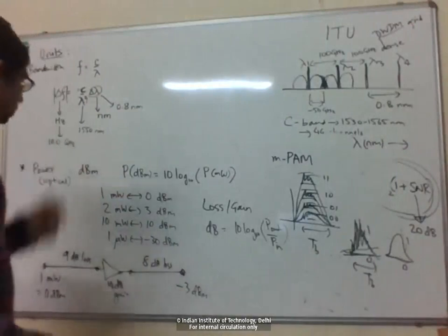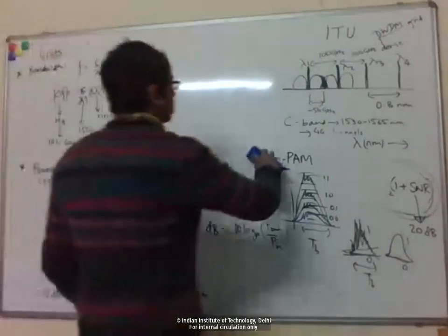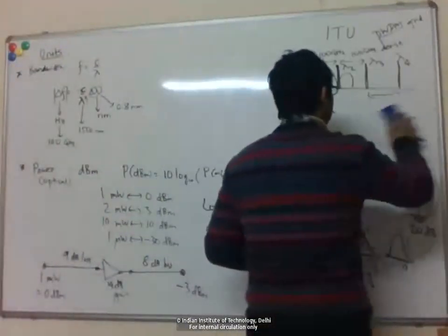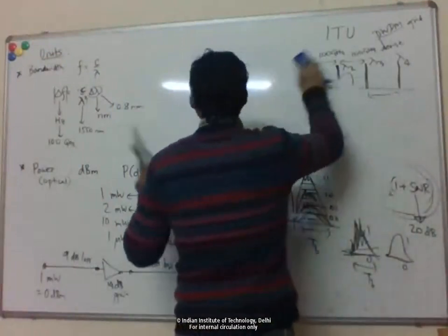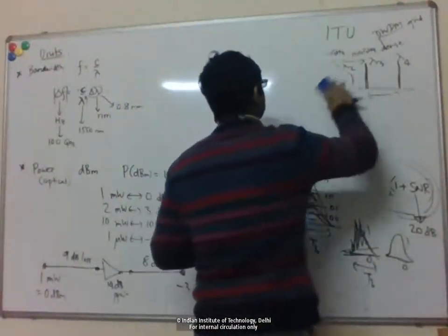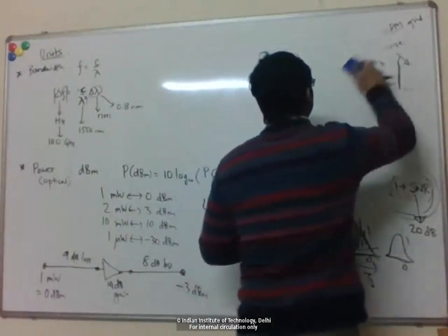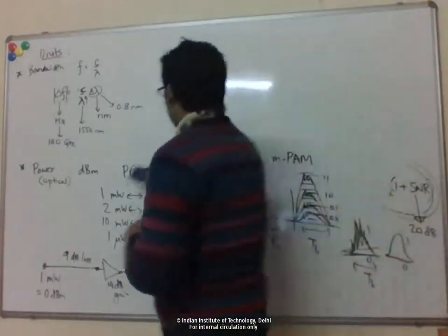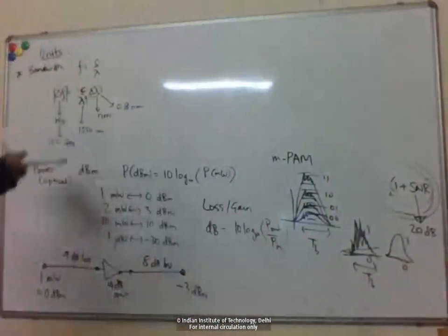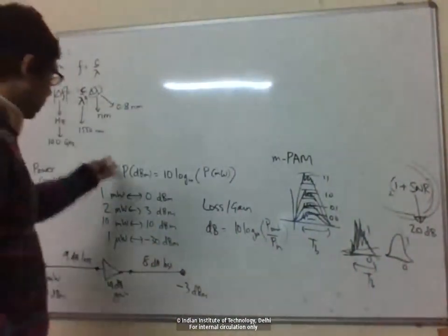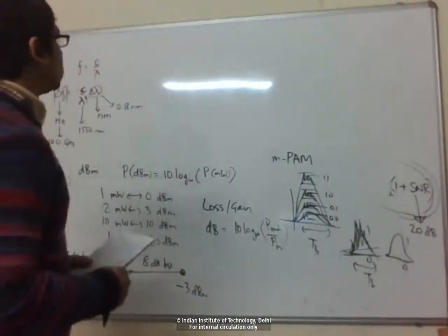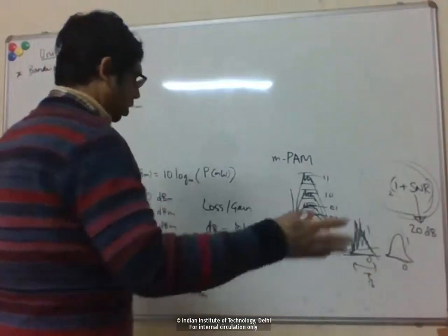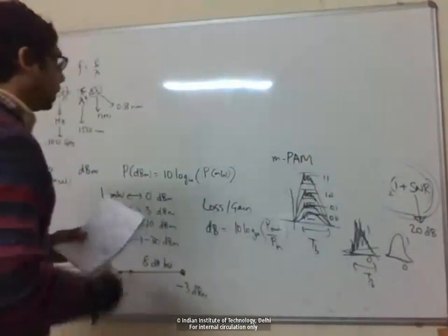Right, so then there is this fiber propagation loss, alpha. We already discussed that in a couple of graphs, and we saw the unit was dB per kilometer. Again, there we have used dB units to be in line with the dB units for power and loss and gain, so that we can easily calculate the total loss and gain and the powers in an optical link.